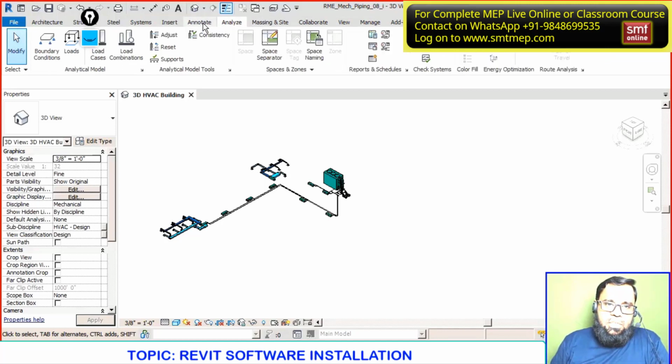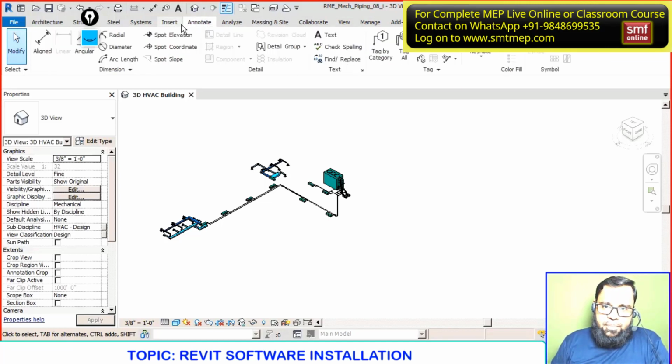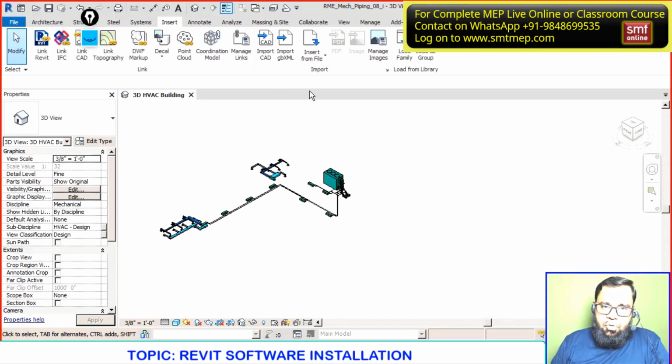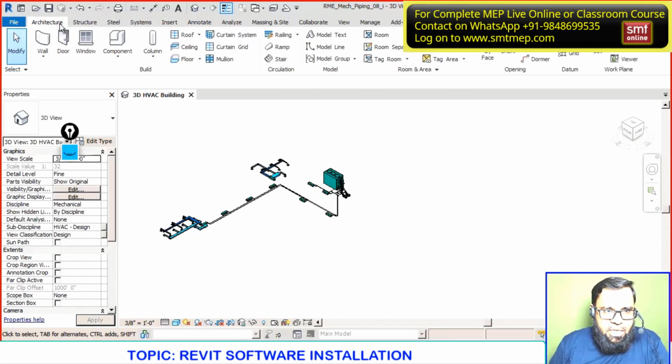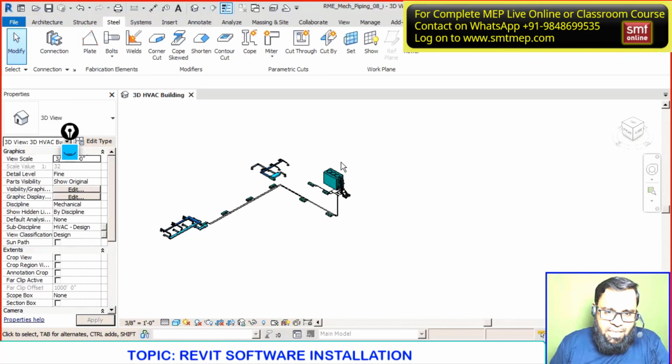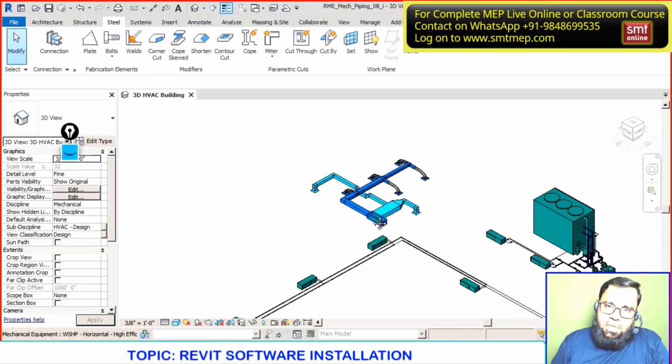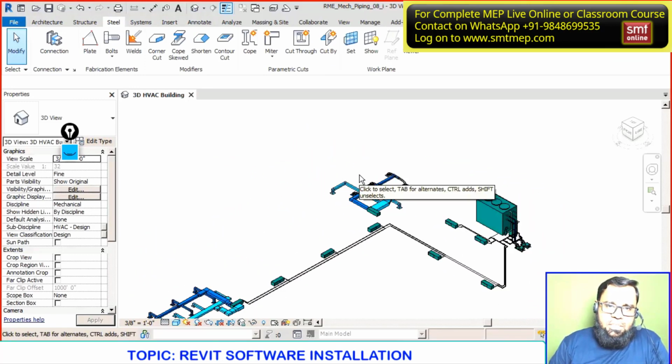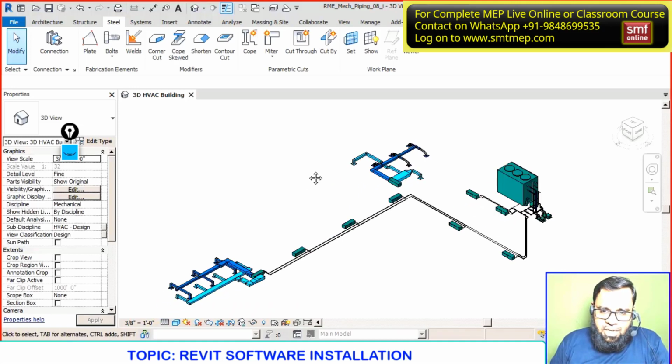That is also one reason learning Revit with a project is required. Without a project, if you learn Revit, you may miss a number of tools. I cannot find the tool called Generate Layout in any of the menus, and it will activate only after completing the logical connection. One example like this: after logical connection there's physical connection, then the designing, etc. Even the design tools will activate after completing the previous steps. So following the order is important in Revit. You must follow the order.